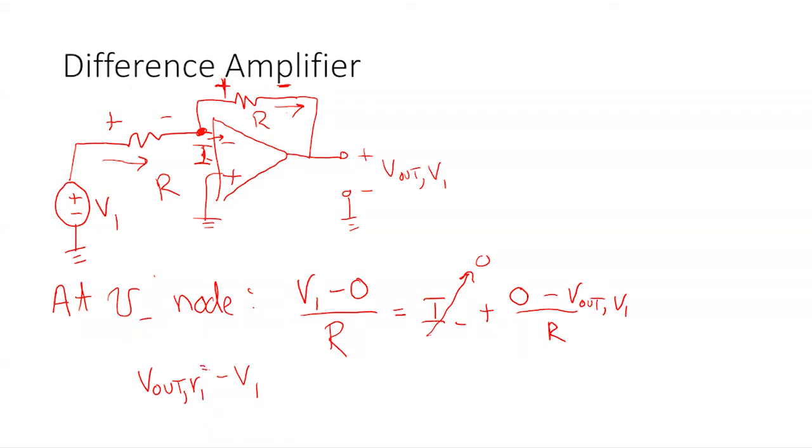Why is V1 positive? Like, if you're doing, I don't know, I always get confused when you do that. Is it minus V1 or plus V1? I know why she does it, because I do it the same way as her. So okay, the question that Kate is asking here is, this gets into the way that I do KCLs, the way I learned it, right? So I just define my current directions and I define the voltages across the resistors.